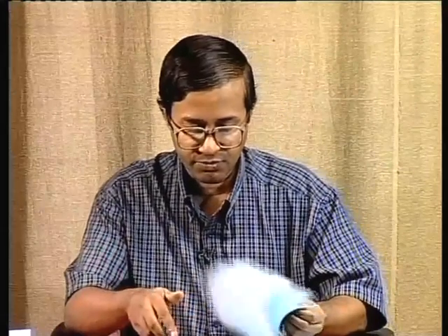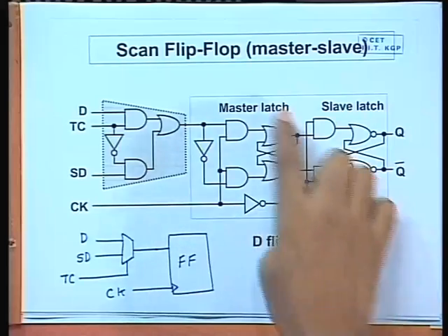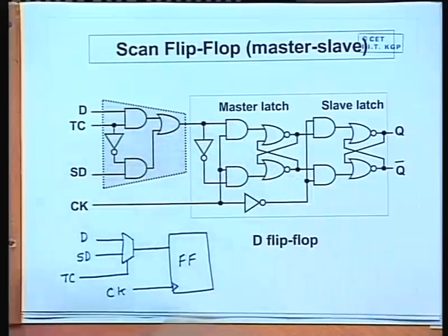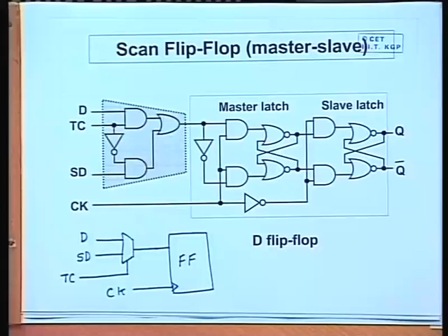Now, when you are converting a flip-flop into a scan flip-flop, if you recall, you are adding a multiplexer in the input stage, which means 4 additional gates. So, if you just look at that diagram once more, here the original flip-flop circuit without this required 10 gates. To make it a scan flip-flop, you need 4 additional gates. This is something to remember.